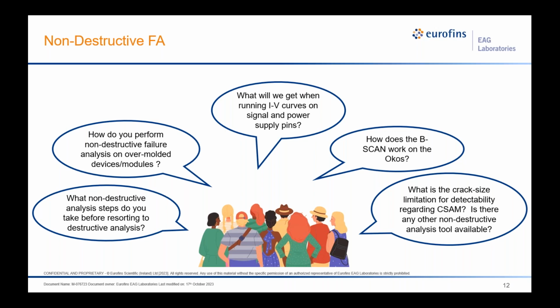Great. And this next question is a little bit kind of related, and maybe you can answer that. How do you perform non-destructive failure analysis on overmolded devices / modules? Sure, yeah. In an overmolded device or like a multi-chip module, there's going to be a lot of interconnects depending on how things are connected, and that means that there are lots of physical interfaces that could be problematic. And so whether it's X-ray imaging, scanning acoustic microscopy, CT scans or reconstructions, curve tracing, time domain reflectometry, there are a lot of great non-destructive techniques to help identify some of these anomalies before we have to decide on how we're going to actually conclusively say what the problem is.